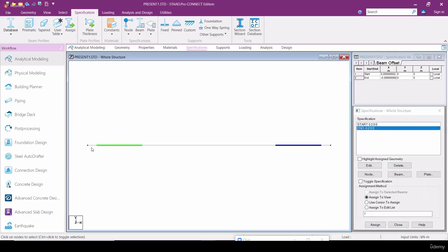If you observe this, the portion where we have given an offset, you get hidden lines. If you offset this beam, the load will not apply at this point, right? Technically, if we are applying load on the full length of the beam, and you are giving an offset, the load will be nullified here. Thus the moment in this beam will get somewhat reduced.